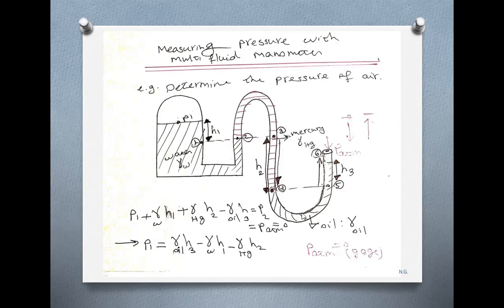When you add all of those, then you reach here, the pressure here on top is equal to the pressure of atmosphere, right? So you start from one end, and try to reach the other end through this U-tube. When you reach this point, then you know at this point it is equal to the pressure of atmosphere, right? Yeah, that makes sense. Thanks. Of course.